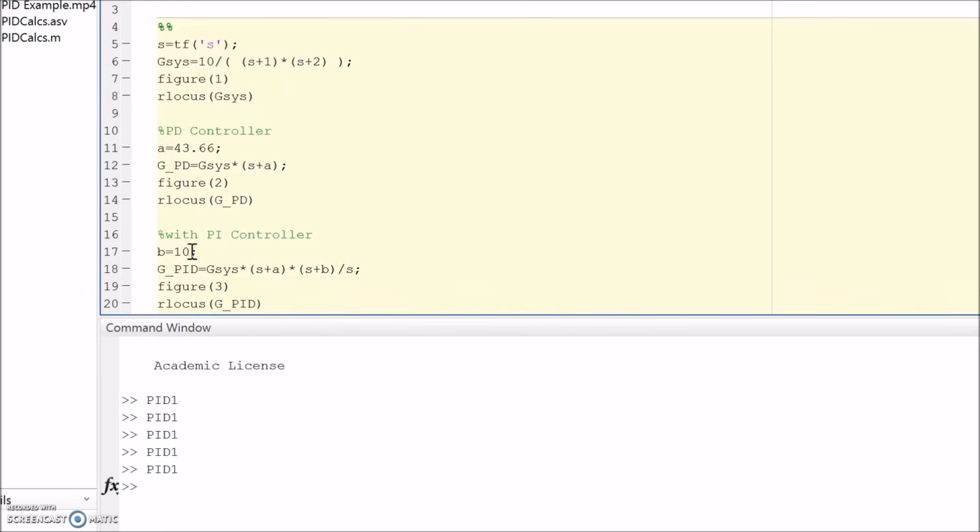So yeah, I'm going to go back to my 0.1. That looked okay. Didn't really have too much of a difference for the two root locus diagrams before and after inserting that extra I part. So yeah. And just remember that if you're in an exam, you don't really have the opportunity to check that. So just pick a small number and say that you assume that pole 0 cancellation occurs.